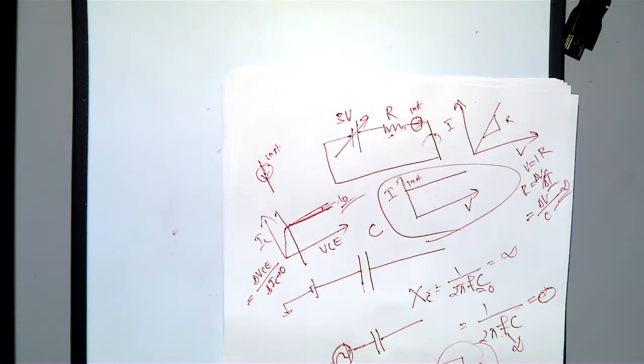These all grounds are connected to the same point. In this example, a resistor is placed between the power supply and the collector, therefore providing an output voltage. See, you can get an output voltage, because this output voltage we are measuring. So here we are measuring voltage between this point and the ground. Then actually what we are measuring is a voltage drop across this RC, because this point is same as this point, this ground is same as this ground.